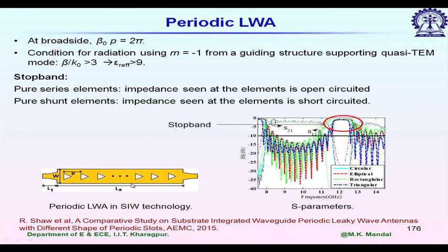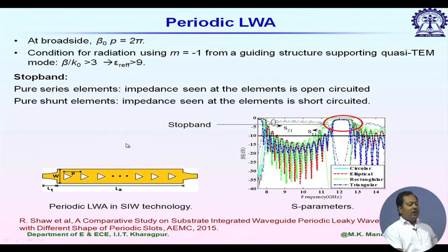Input impedance is becoming infinite, so the waveguide no longer accepts any power, and we do not have any radiation. It is shown by this red circle. Now, if I continue increasing frequency, then again we have radiation from this upper band. In this part, this beam will enter the first quadrant, and we have radiation in the forward quadrant.